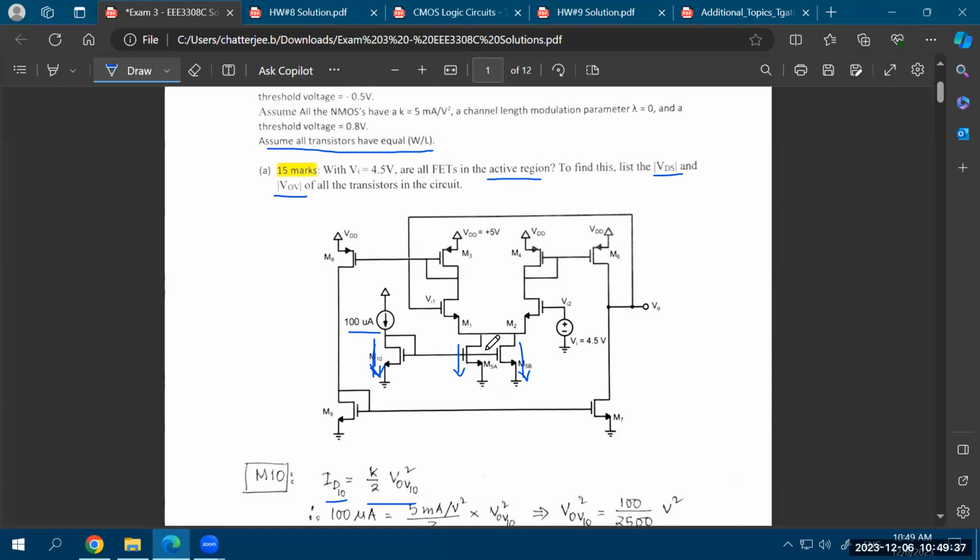But the way we are simplifying this is that we're saying there are two transistors in parallel. So each of them carries the same 100 microampere current, right? That's, again, by definition from the current mirrors. And because the current in the tail transistor gets divided equally in the two branches, 100 microampere current will flow here, again 100 microampere current will flow here.